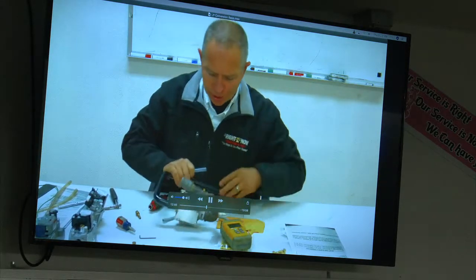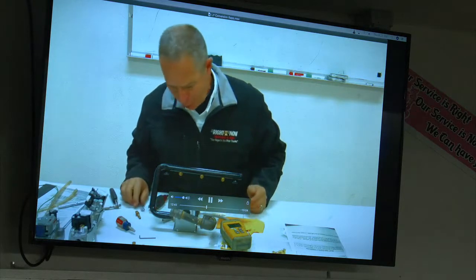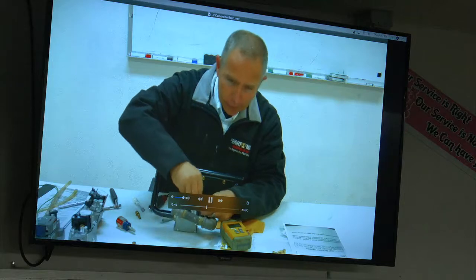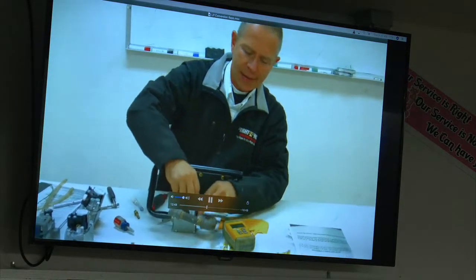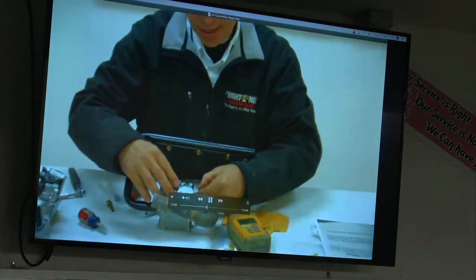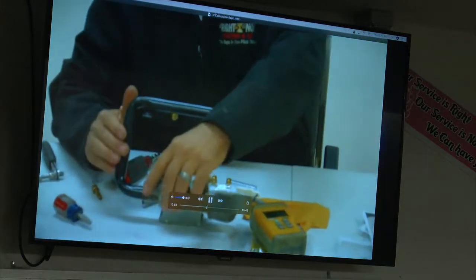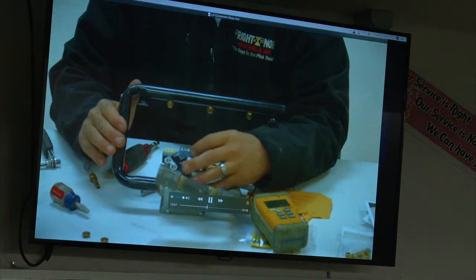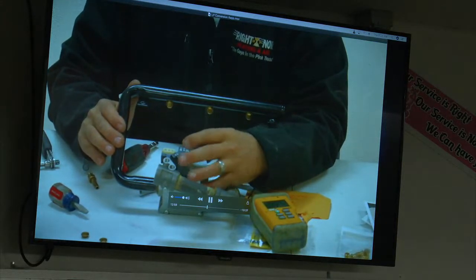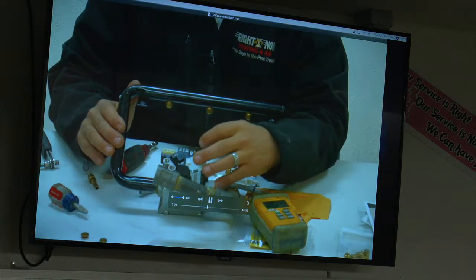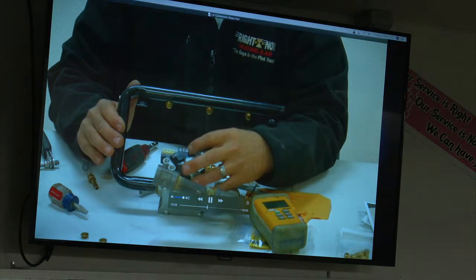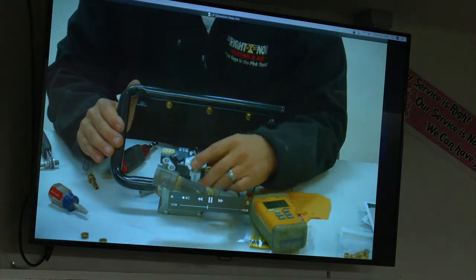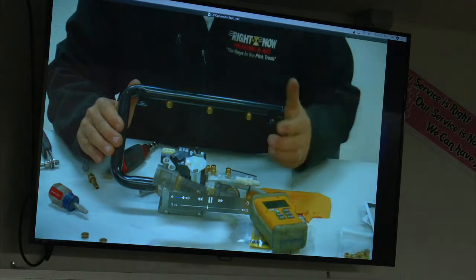And we're going to go to the manifold side and check our pressures there. We're going to take our Allen wrench, obviously, and tighten that down and make sure that it's not leaking. Now we're going to turn the gas back on. I do not recommend snapping the switch on the gas valve any more than you absolutely have to. It's a very inexpensive on-off switch, and I've had them where they've actually broke, brand new. So I would recommend always using the safety shutoff.